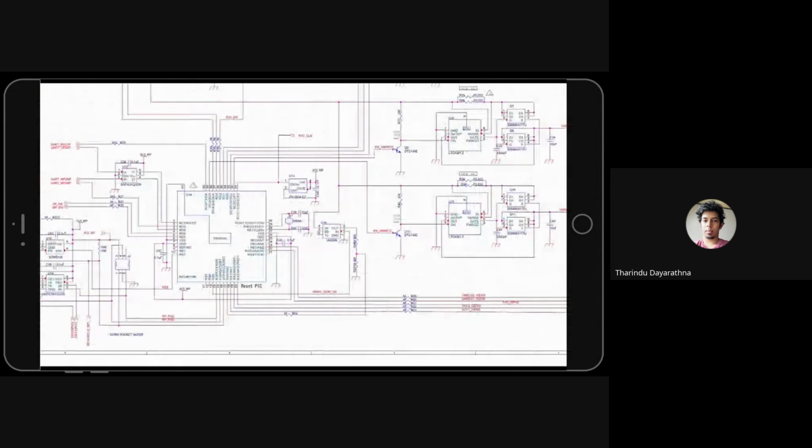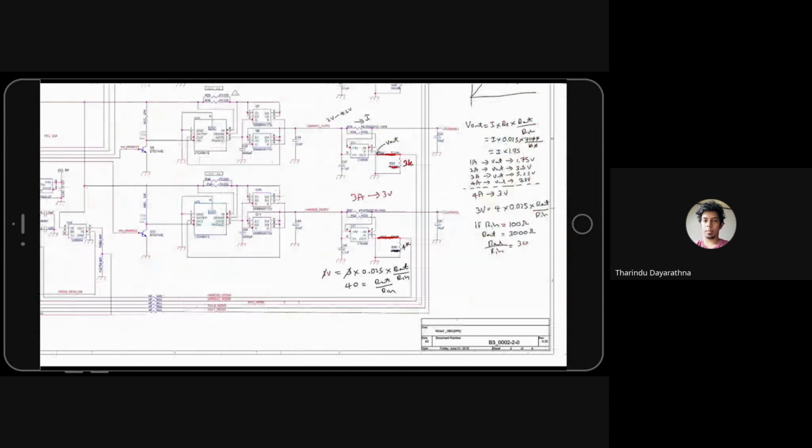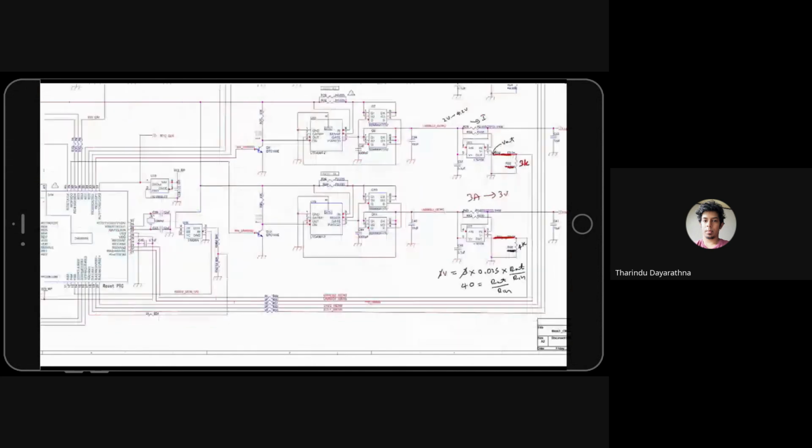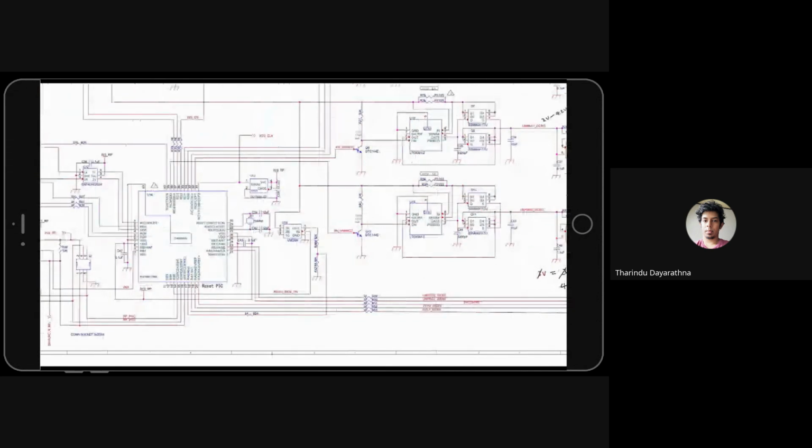So this is very, very important. You must measure this at some interval. In burst 3, every 90 seconds, reset the PIC, measure those currents and save them in the flash memory. Those are the housekeeping data. Very important things.